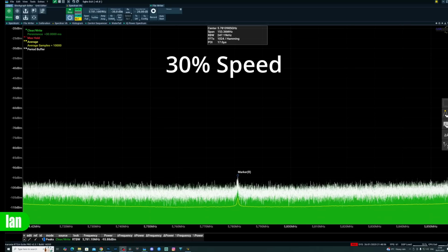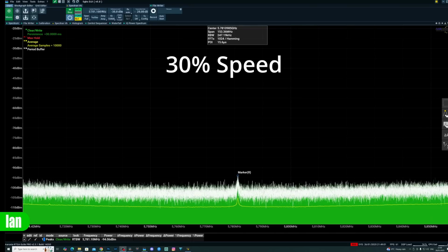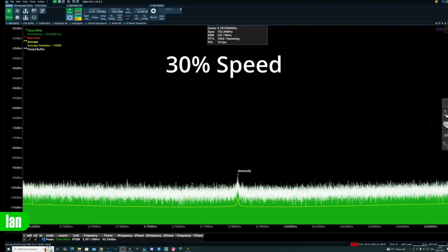Now, one quirk I have found, though, in all of the RF behavior is what happens when you power up the ear unit. As I've said already, the goggles do not transmit when the ear unit is powered down. However, when you do power up the ear unit, there appears to be a bit of a band scan where it chucks a couple of carriers onto some specific frequencies before jumping onto the last channel used.